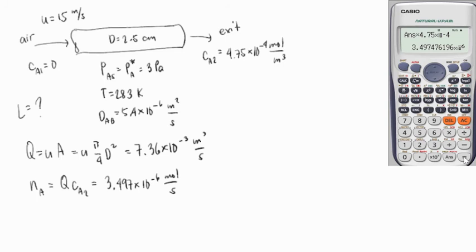And then if you go back to our previously derived equation for the rate of mass transfer, that is N sub A is equal to pi d L times Kc times delta Ca. Do not be confused by the delta Ca here. The delta Ca is not exit minus entry. Or we can also say that delta Ca is not equal to Ca2 minus Ca1. Okay? Delta Ca here pertains to a driving force. And the driving force is the concentration difference.